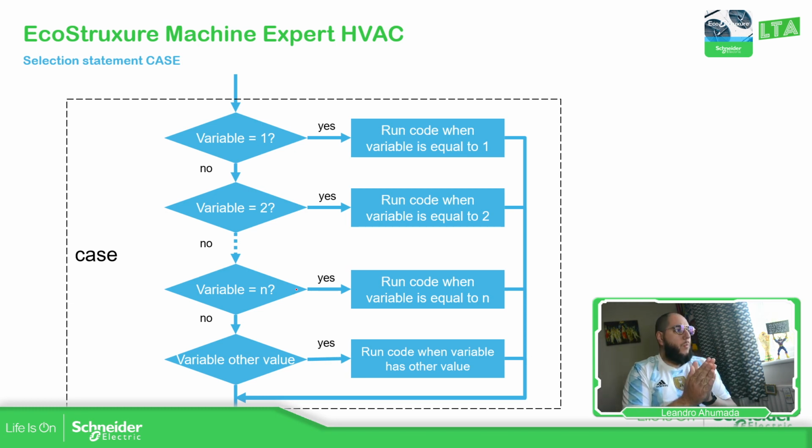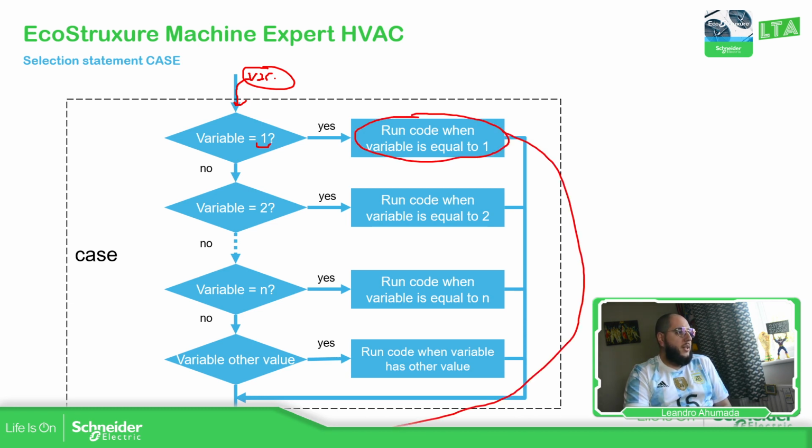Okay, so the case is a syntax that can be used in structured text. As it shows here, we just go with a variable, enter it here in the box, and then it starts asking, is this variable equal to one or another one that we define? But let's just follow this. Number one, if it's yes, then you just execute one part of the code and then just go to the end and get out of the block.